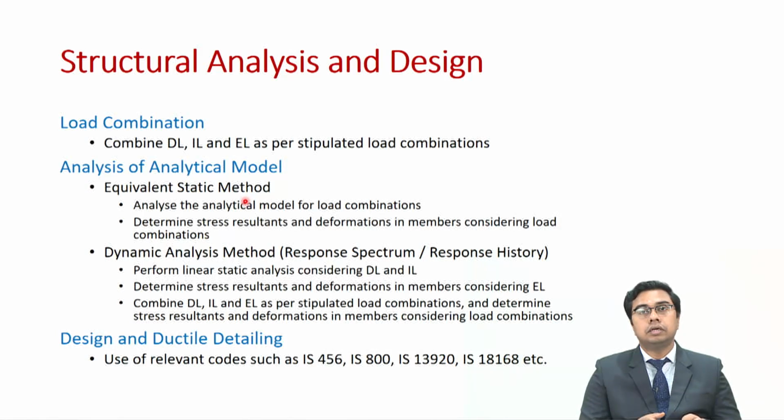In case you are using a dynamic analysis method, that is either response spectrum or response history method, then in that case we will first perform linear static analysis considering dead load and imposed load only, and then we will determine the stress resultant and deformations in members considering the earthquake load, and then we will combine all these loads as per the stipulated load combination that we have seen and determine the stress resultants and deformations in members considering load combination.